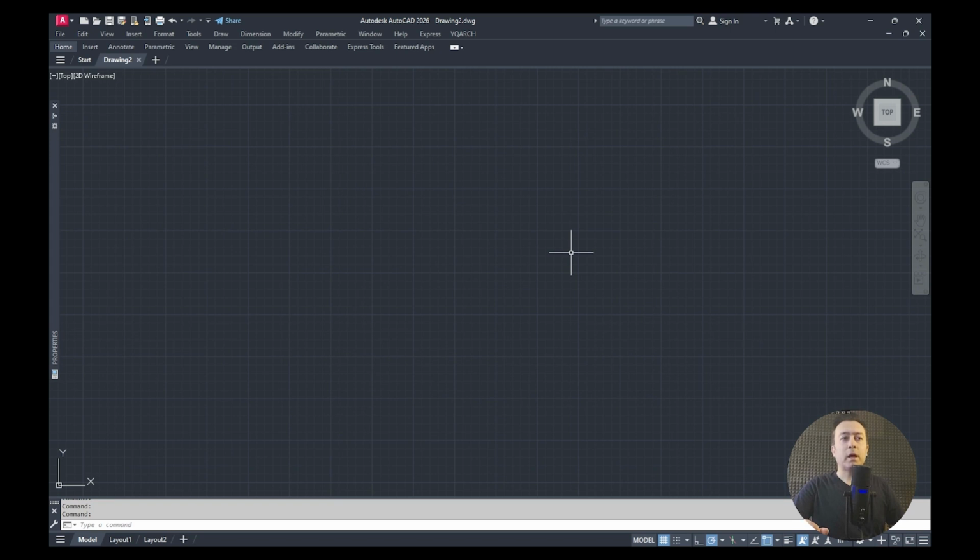For the initial steps, there are a few things you need to know. The first thing is that in Autocad I have a mouse cursor symbol. This same symbol that's moving in the middle of the screen right now is what we call the mouse cursor, and it's interacting with me. When it's a plus sign with a small square in the middle, just like you can see right now, that's the state it's in. It's just a plus sign, and there's a little square in the center of it. This means that I'm not currently in any command. But when it enters a command, its appearance changes. For example, if I enter a command that lets me draw something in the software, it just turns into an empty plus sign. That square in the middle disappears.